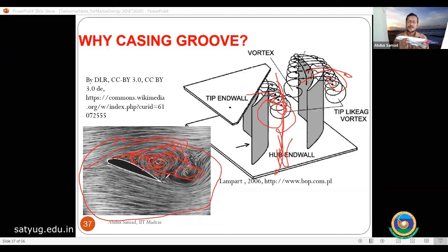So in a turbine also, that's happening. If you have improper lift or the fluid velocity is changing, let's say from laminar to turbulence quickly and the fluid velocity is very high, in that case again flow separation will be there. If flow separation is not controlled, then the aircraft cannot get lift. Similar phenomena occur in turbines also. So in a turbine, if we cannot control the flow separation, we cannot get proper lift or energy or power. So we have to control this. That's why we introduced the tip grooving mechanism.